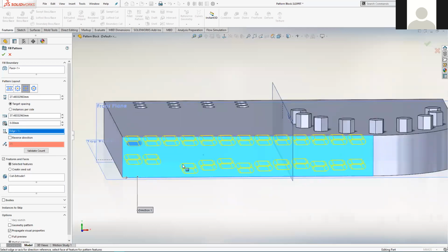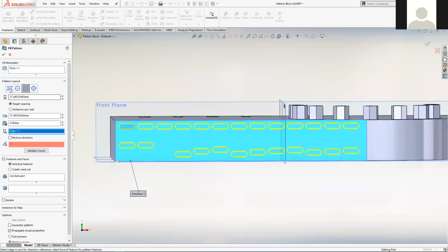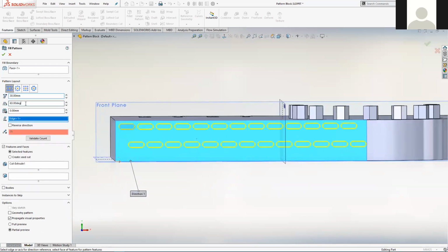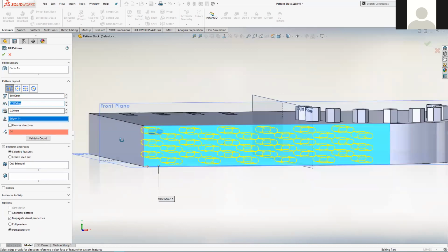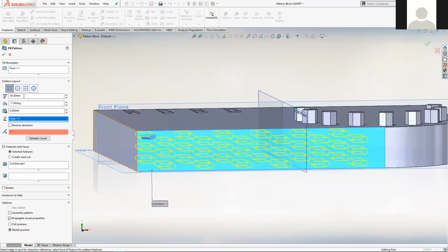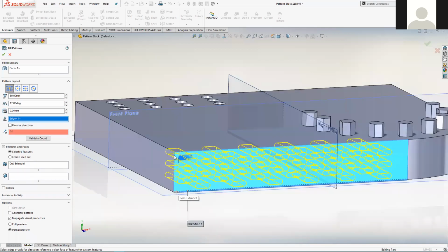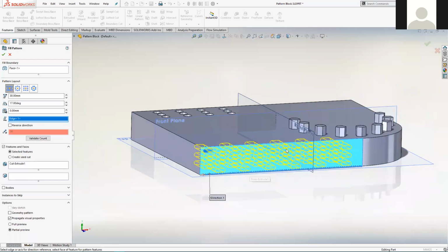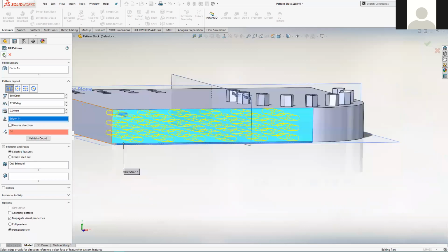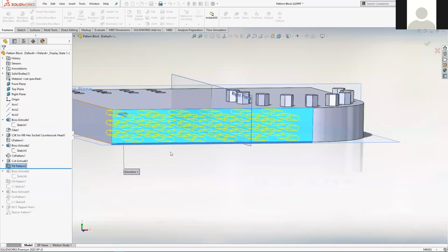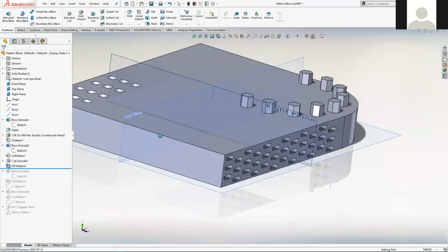So yeah, we're not going to play with all the options in there, but know that it can be useful in certain situations. So anyway, what were we going to leave it set on? I think we're on about 17 degrees there. Yeah. So if you set everything back to that, that's a reasonable way to leave it. So 30 millimeters, 17 degrees, 0 on the margin, and the edge that you want selected was that original bottom edge rather than the vertical one that we selected. And then when you get all the settings like that, you can OK the pattern. And that's the sort of thing that you end up with.